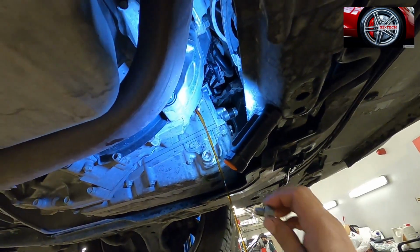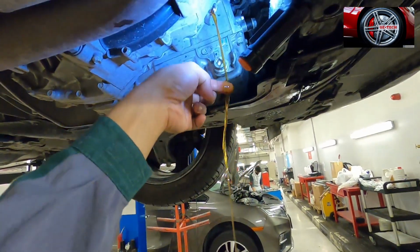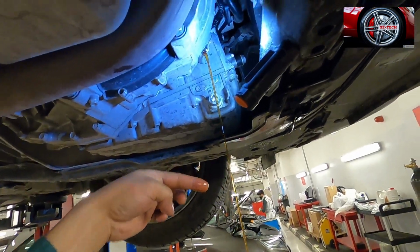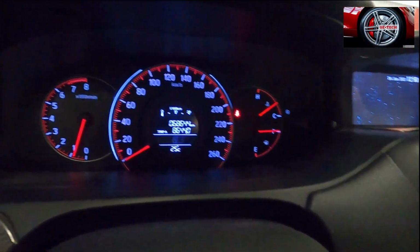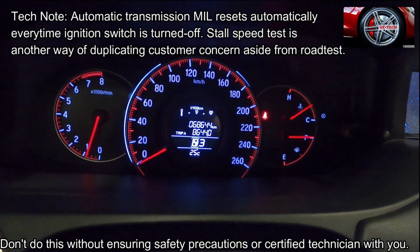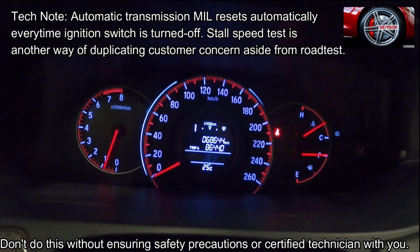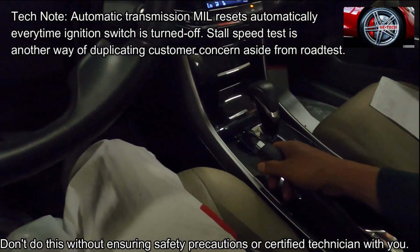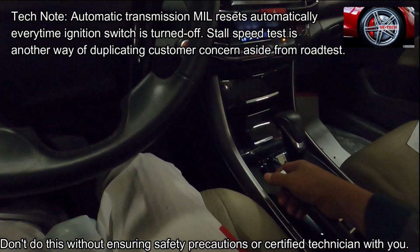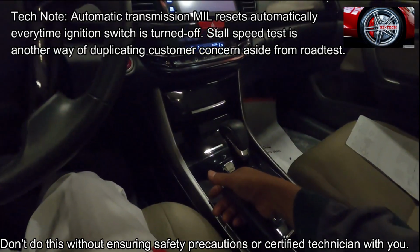So the CVT fluid and condition still good. On this MIL, we already have a clue that there is a problem in transmission. So let's confirm it. Let's isolate it using the first step of reproducing the problem, let's do the stall speed test.